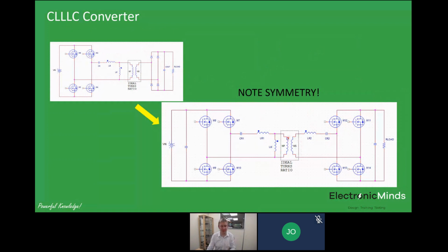So this is a really symmetrical system, and when we're looking at the development of e-mobility and vehicle-to-grid type applications, the ability of your electric vehicle charger to either charge energy into the battery or, in the same power stage, send energy back into the grid, that's quite a neat feature. And especially when you can do it at the sort of efficiency levels, 98-ish%, that is possible with this sort of a resonant topology.